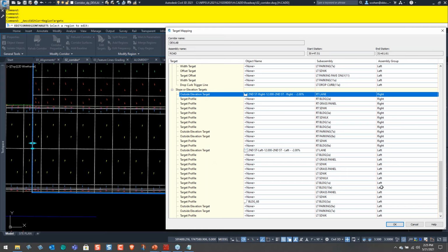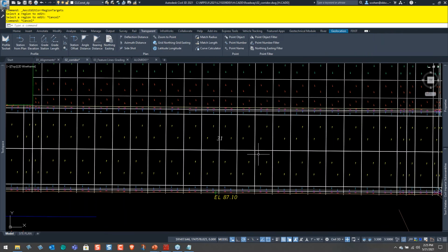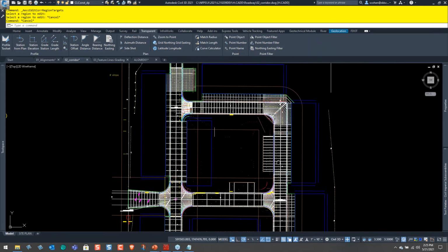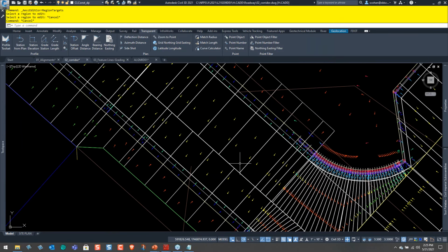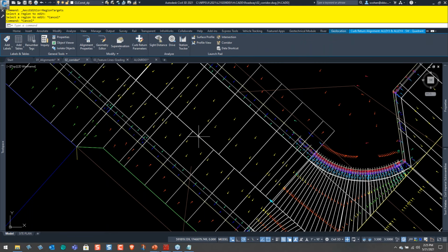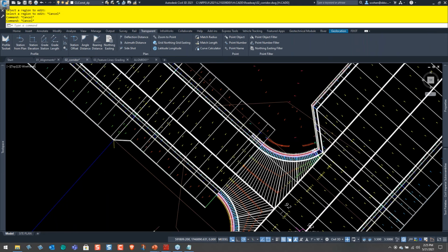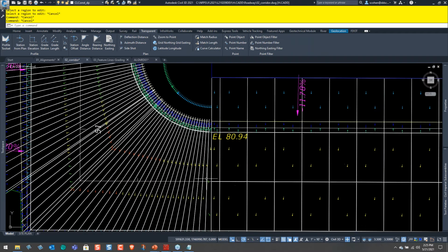It updates automatically. The other thing too is this site changes roadway width quite a bit because we're trying to fit buildings, we're doing all kinds of stuff. In fact, in one spot we were so tight we had to make it one way. So down here, if you look, this is actually a lot smaller width, okay? So I don't want to have to worry about that. Whatever my offset alignments are, I simply target those. You can see here, I have an offset alignment for every road, and I simply target that by targeting its alignment and profile. You can see here by the arrows, this is a nice, very easy way to quickly see which way the water is going.